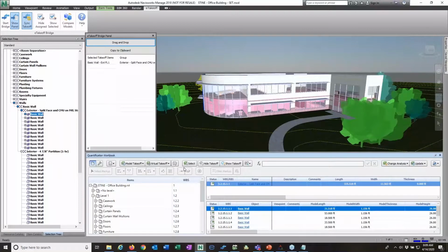Number one is we may have to rejigger our assemblies just a bit, because some of the information that we typically calculated in estimating is now provided for us in the model. For example, if I wanted to get the volume of that wall for some reason, maybe I was filling the block cells or something like that, I don't need to calculate it. I can just get the volume right here.